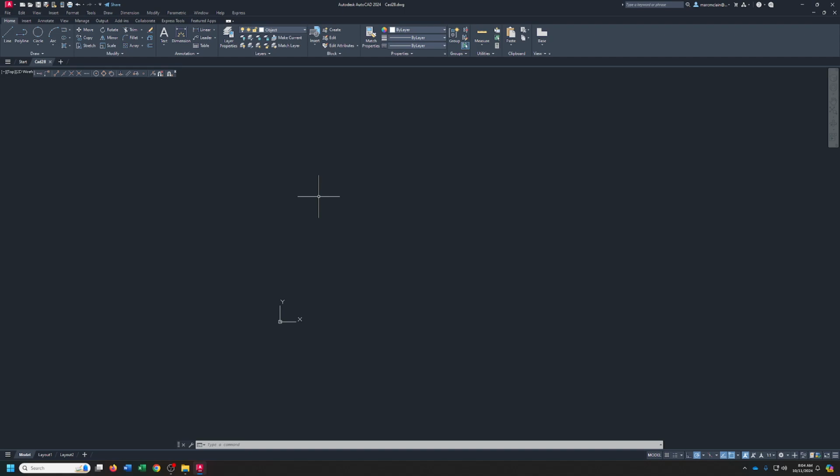Now, if you'll notice, that thing has a rounded front. The rounded front on that has a radius of 1.25. What we want to do is add that 1.25 to the 3.25 so that our bottom line is 4.5. Okay, so we're going to start here. We're going to come down 1.75, and then we're going to go out 4.5, and then we're going to go up 0.5.